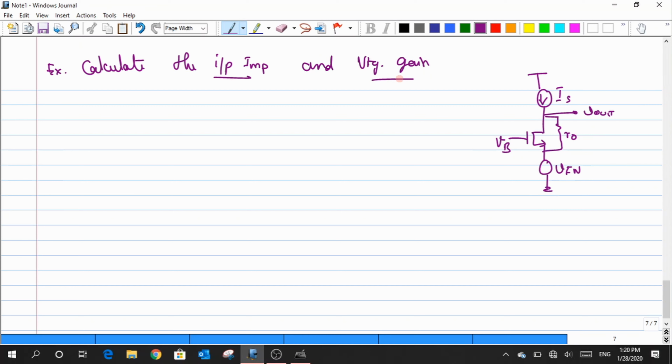So now what happens in that case? R naught was connected to our drain resistance, right? Right now the drain resistance is infinity. So R naught, when it gets added to it, is again infinity, okay? If you could recollect, when I had a resistance RD here, we ended up having the value of Rin as something like R naught plus RD divided by GM prime R naught, right?